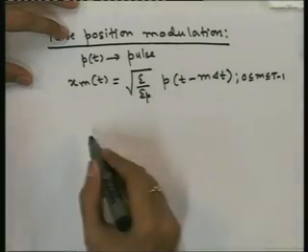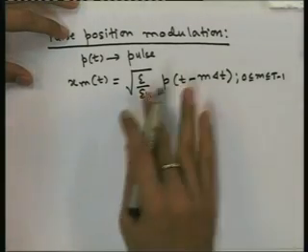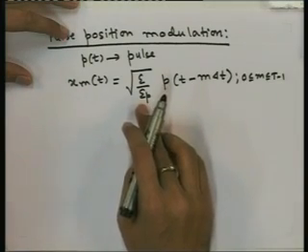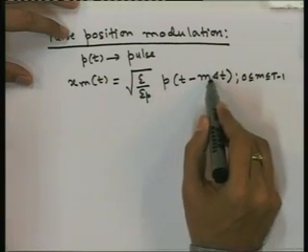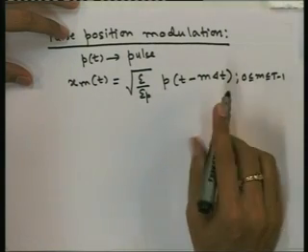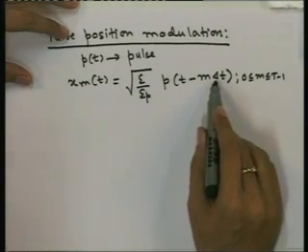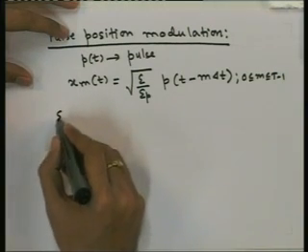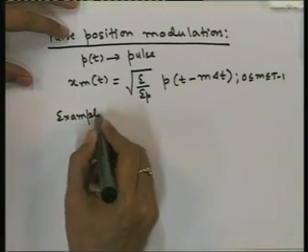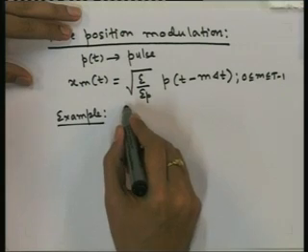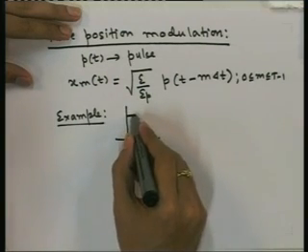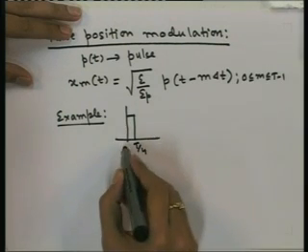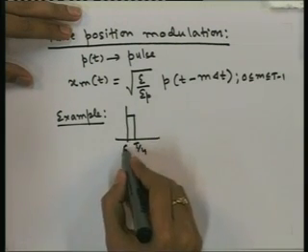So this is the signal set. What are we doing? We are taking a fixed pulse, the fixed amplitude is not changed, whereas we are just shifting the pulse by different multiples of delta t. So let us take an example. If we take this rectangular pulse, say this is T by 4, we want to take 4 PPM, we want to have 4 points.